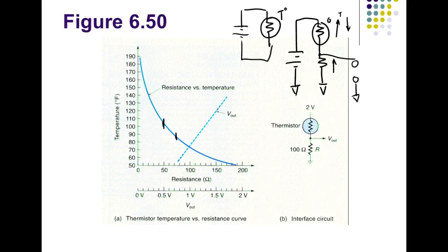So you can buy temperature sensors for these meters right here. But those are usually thermocouples, by the way. Those are not semiconductors. Thermistors, they're not linear. That's their biggest problem. But we work around that, right? Everybody okay?